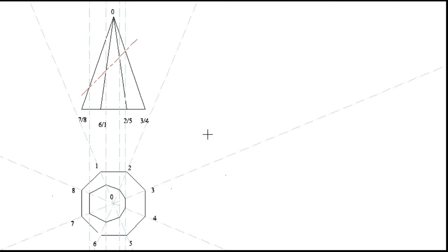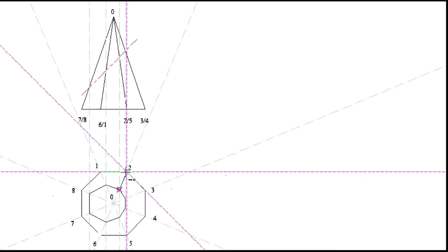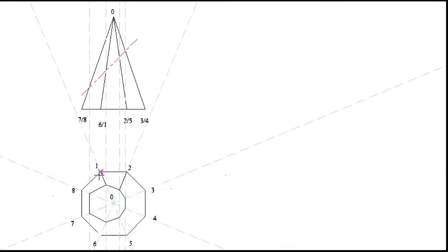After joining all my points, I will have a shape like this one. So to finish my top view, I will join these lines. So now this is how my top view will look after this cutting plane AA has taken effect. To show that this part is being removed, I have to show it by hatching. So now after hatching here at 45 degrees, my top view is complete.